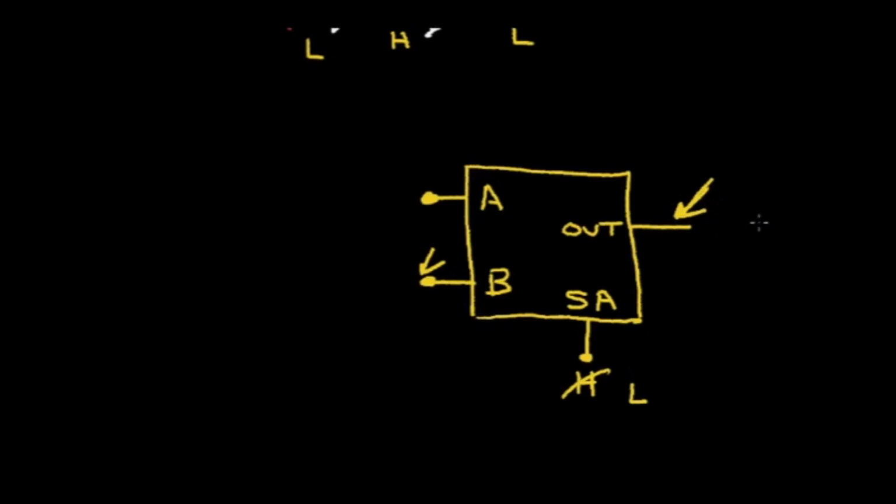So this gives you some idea of the different circuits that we can do. Just starting with an inverter and a CMOS switch, we can turn that into a tri-state driver. And we can take the tri-state driver and an inverter and create a latch circuit to store data. And then just by making a very simple change to that latch circuit, by removing one connection, we can turn that circuit into a MUX or a multiplexer.